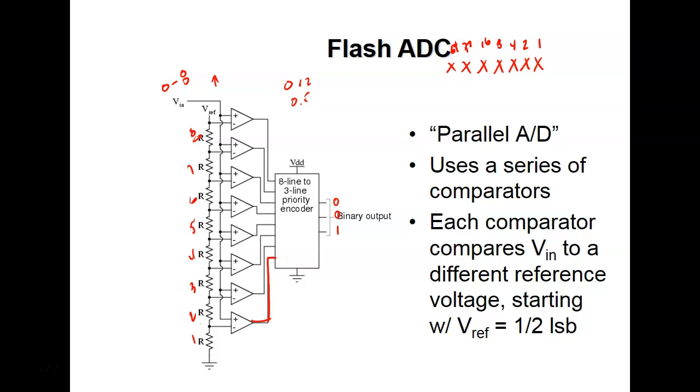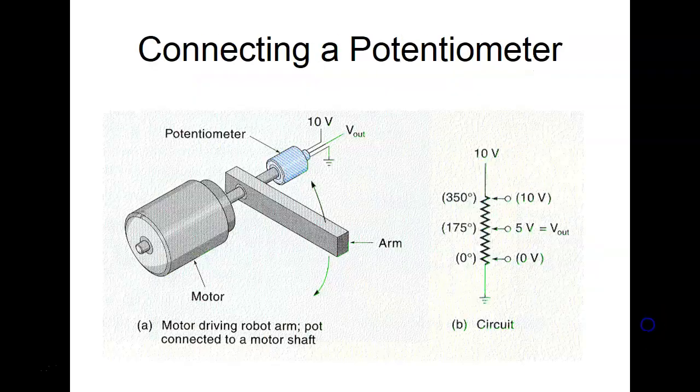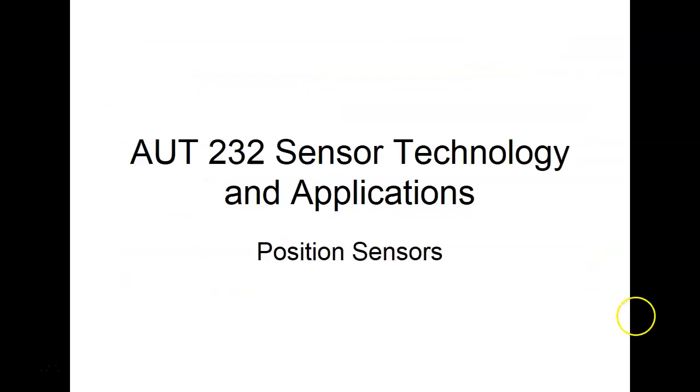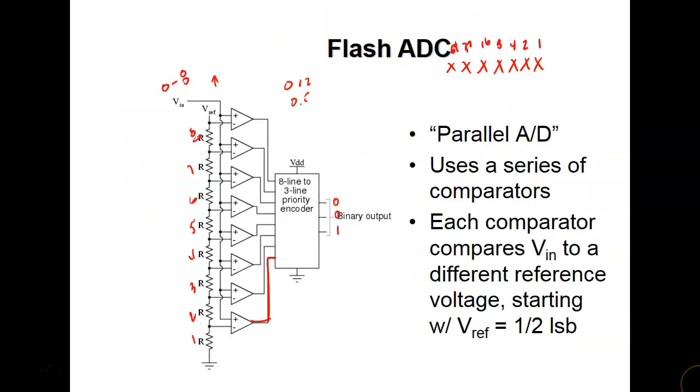So what happens is this guy would come into this decoder, and it would say, what did I have on the input? I had a 1. And then anything between 1 and 2, it won't notice, right? You understand? If you had 1.2, it would still be 1, 1.3, all the way up until it hit what? 2, and then this guy here would trigger, and my output would go to 2, right? And then it doesn't recognize anything between 2 and 3, but as soon as it got to 3, it would trigger this guy, and this guy right over here would give me a 3.